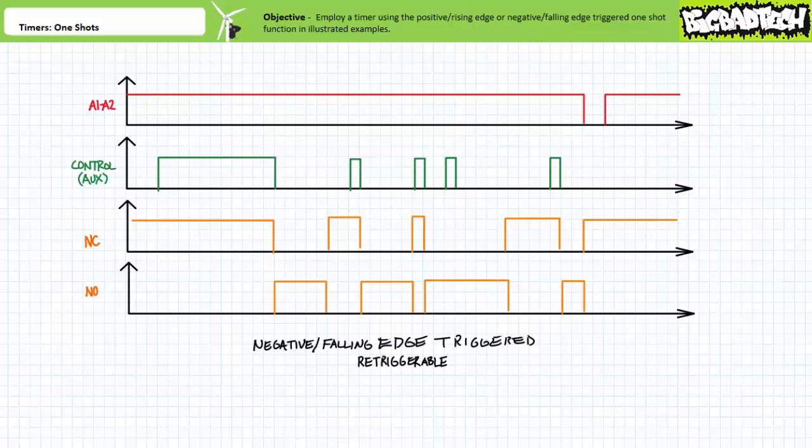Finally, in the interest of completeness, here's yet another timing diagram, only this time for an externally powered, retriggerable, negative edge triggered OneShot set for 5 seconds without a reset. Again, this is an externally powered, retriggerable, negative edge triggered OneShot without a reset.